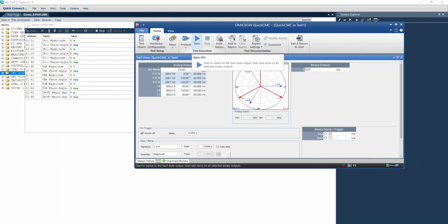So if I just start injecting those values, the 3 voltages and 3 currents, as you can see here, I use the MiCom to measure those. These values should show up here in the measurement in the MiCom. Do it again.